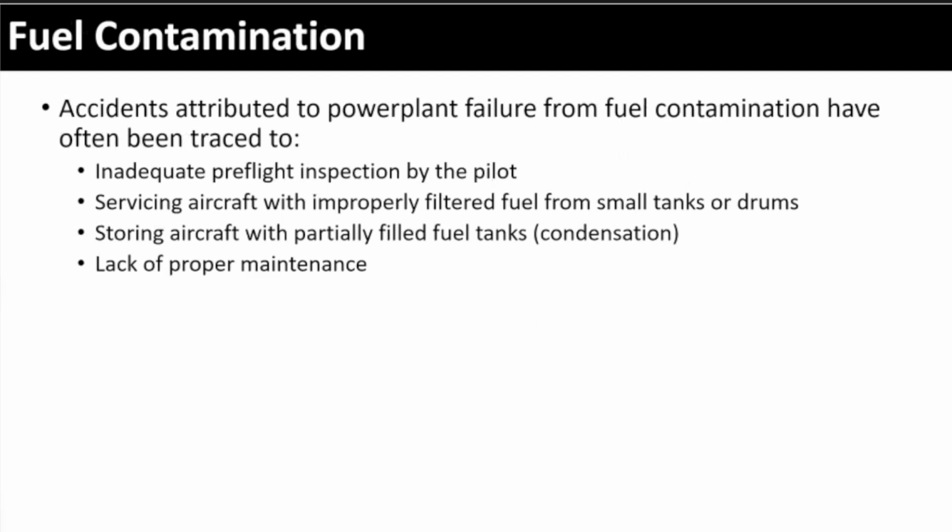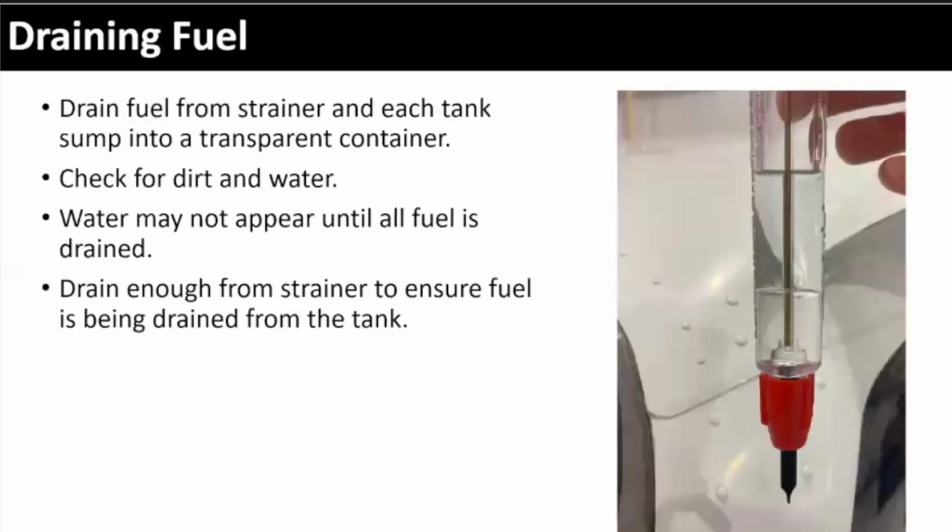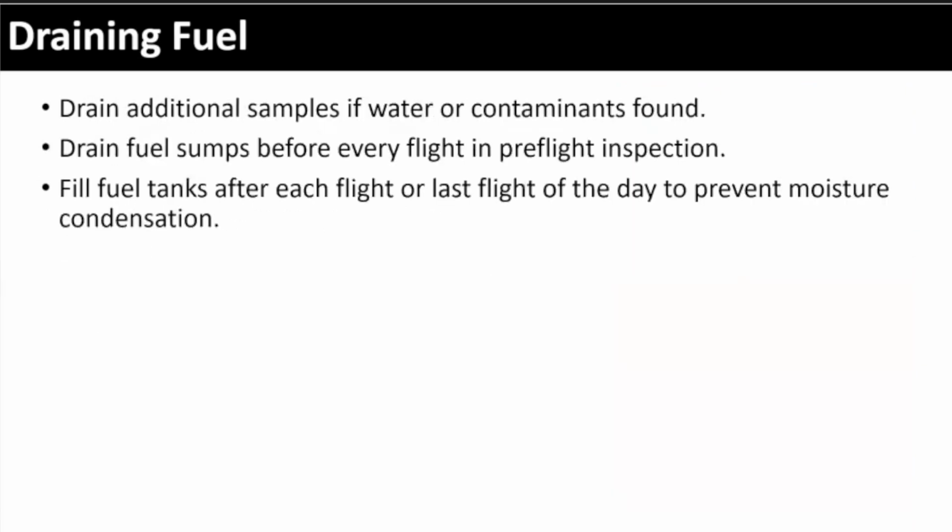All right, I talked about this already. This is all about why we do it, right? We test it because we want to live to fly another day. That's the way I like to put it. If you don't do it the right way and you don't do your due diligence on the fuel supply, it's not going to end well. Okay. Take every strainer, check for dirt, check for water, and keep draining it until it's clear. If it's not clear, don't fly.